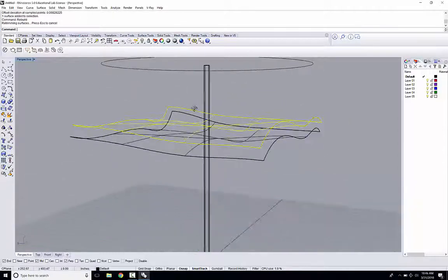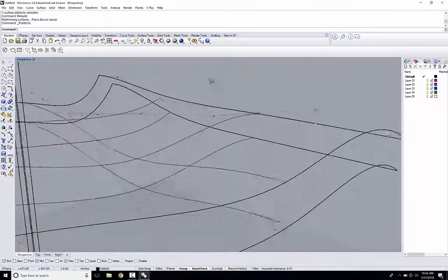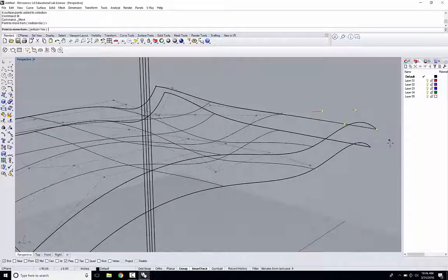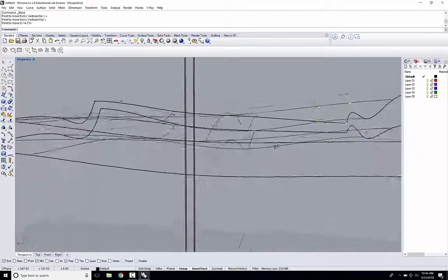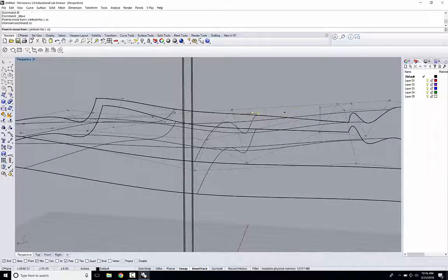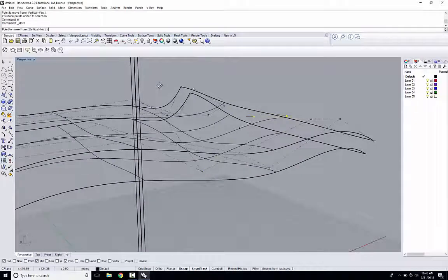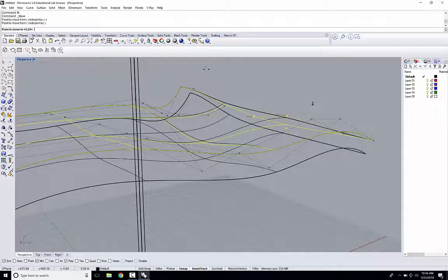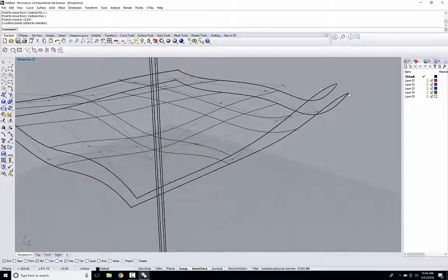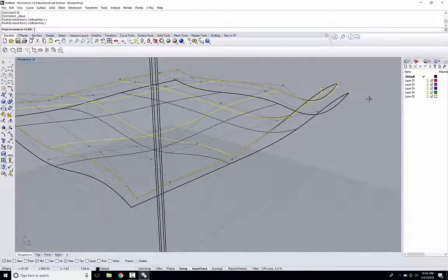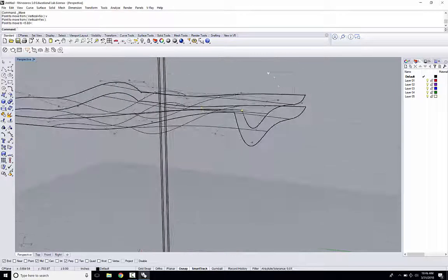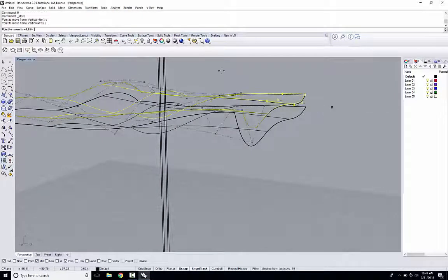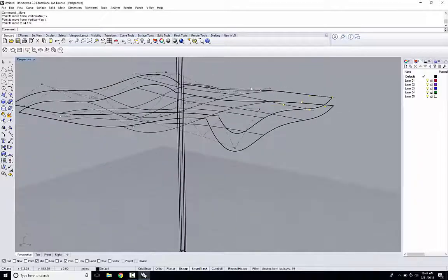Same number of curves. In this case, again, I'm going to manipulate this so that the hexes aren't exactly the same shape. Because I want to keep the depth of this at 8 inches, I'm only going to be moving these. I'm hitting move and vertical to constrain my movements to only vertical moves, and only back down towards the original surface. Sort of reducing the offset in spots.